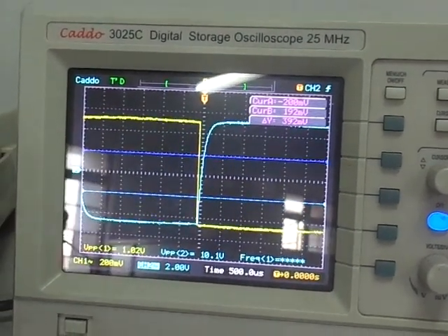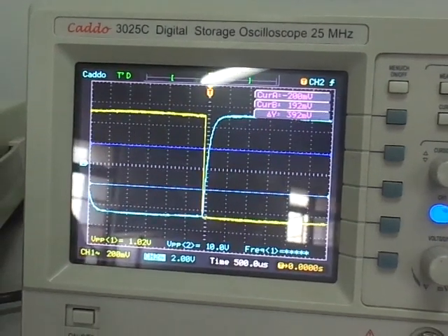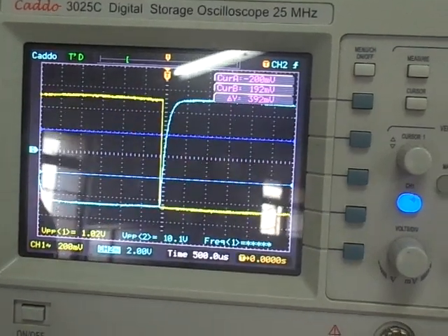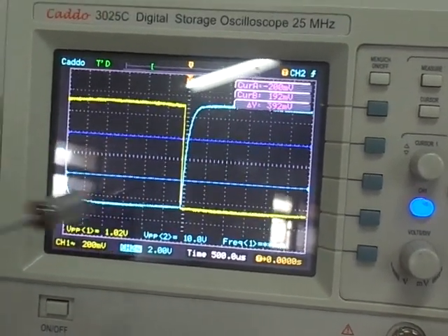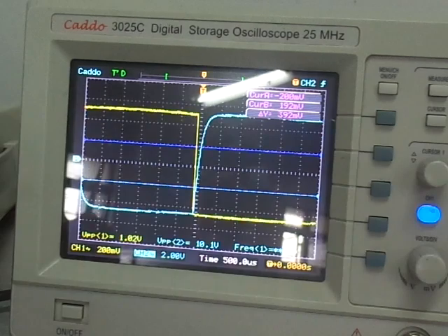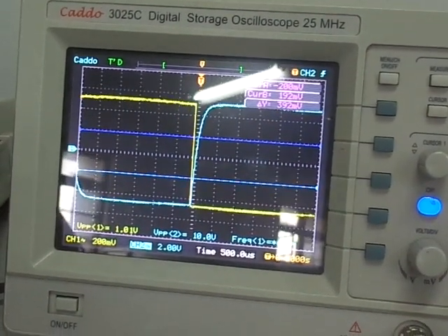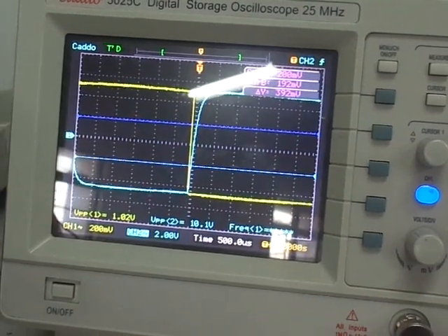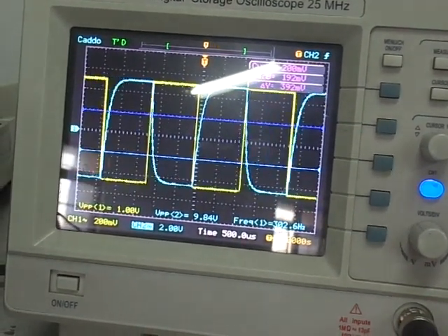We have selected resistive element RF 10 kilo ohm and R1 1 kilo ohm. So gain is 10 and it is an inverting result we are getting. So initially at low frequencies, as we have mentioned, the circuit behaves as an inverting amplifier. Practical integrator behaves as an inverting amplifier. If we select the next frequency now, 500 Hz.